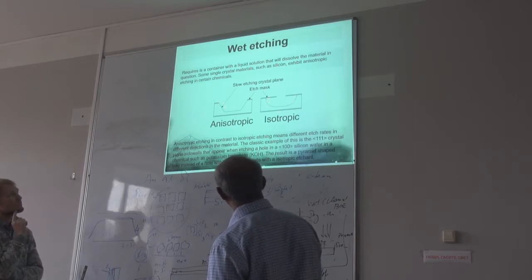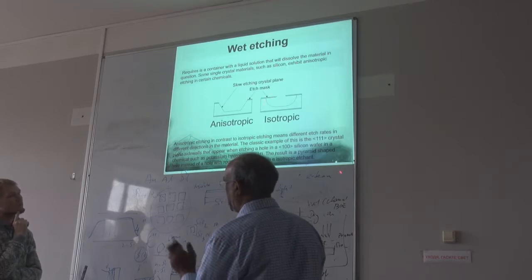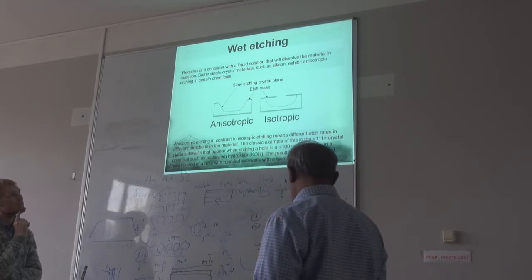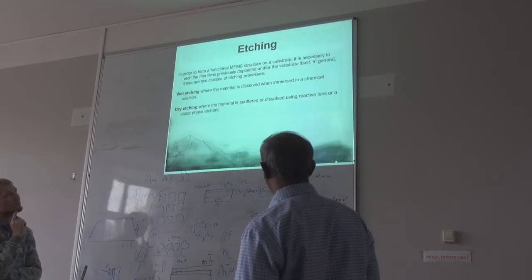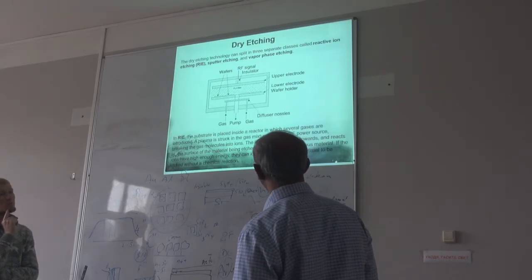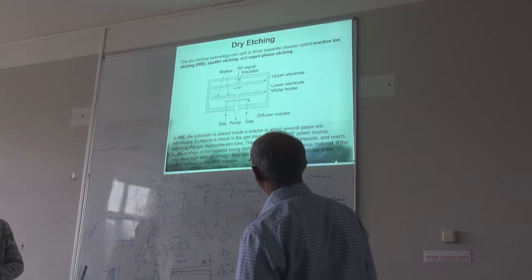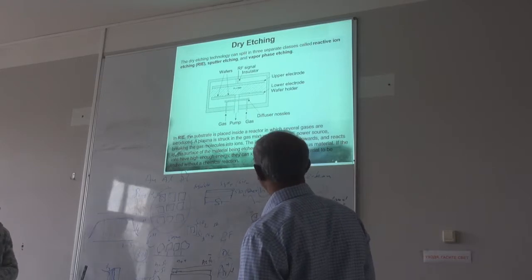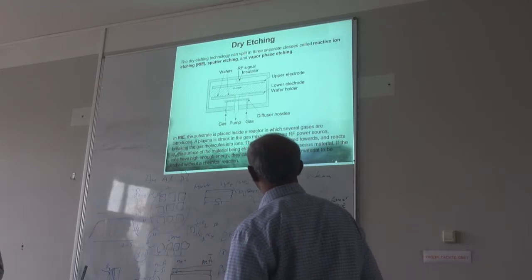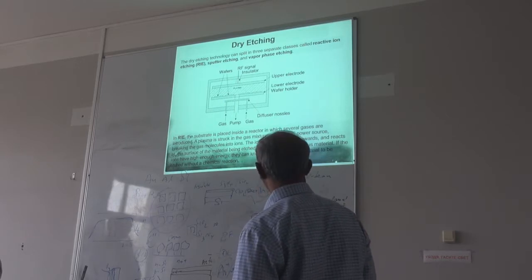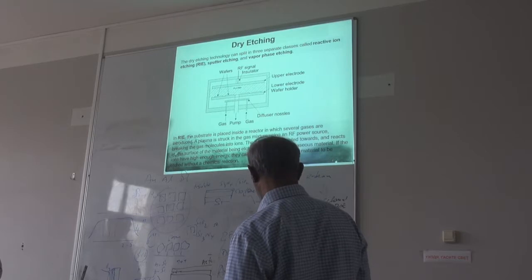Then typically we call this the undercut, and this depth should be pretty much similar in size. So these are some tricks here. Once you get used to it, you can. So this is dry etching, typically put in a plasma, and use whatever gas you can use, xenon gas or other gas. Same RF plasma system.